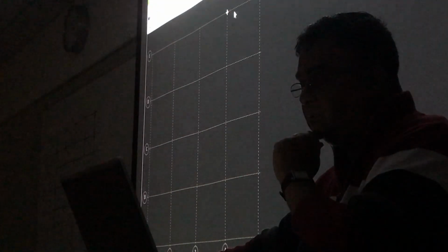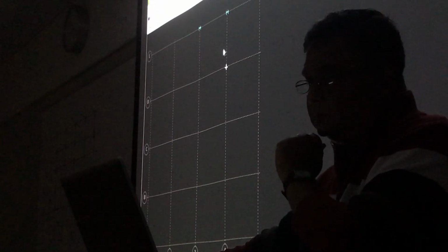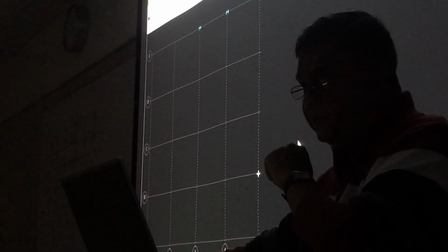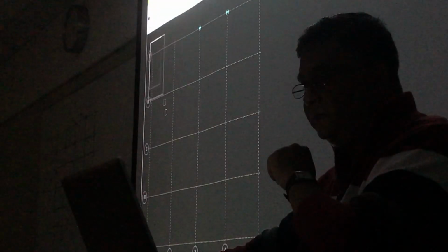You can use cube, rectangular HSS or round HSS if you want. But I like this one because that's more commercial one. So single, if you click on that single, it will click on the single intersections. But if you know that you will have columns everywhere, you can do right click and do a fence, click and fence it.